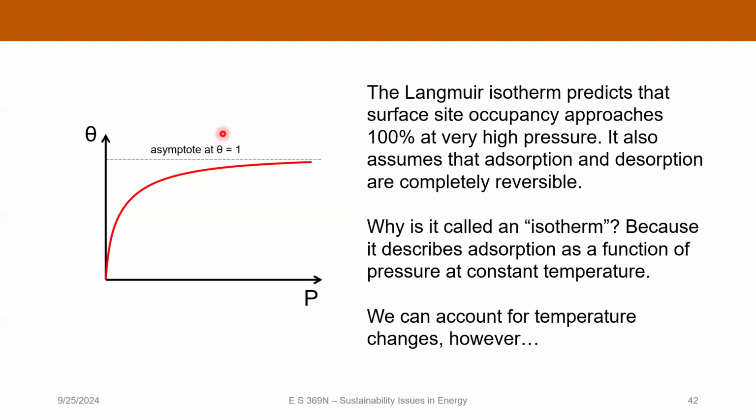So you can design your reactor such that it operates at some elevated pressure, and then when you're ready to do the desorption step, you just pull the pressure down to atmospheric, and all or some of the CO2 will come off. Okay, there are other ways of doing this also, where we can talk about how the temperature can cause this to vary as well.